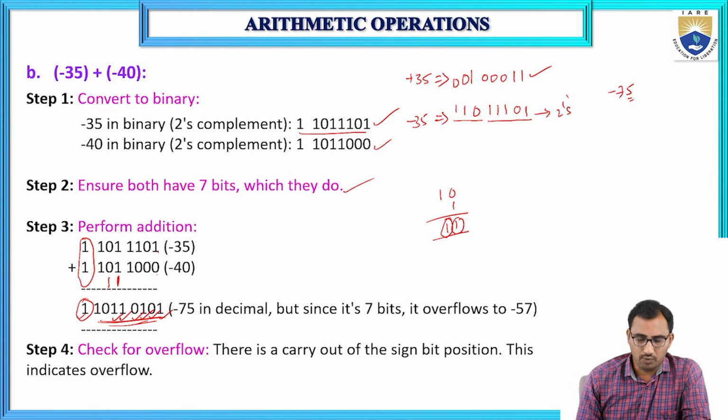Okay. So if you want this value, then for this data we have to perform the 2's complement. First we need to perform 1's complement. So 0, 0, 1, 0, 0. Okay. So for the actual value, leave the MSB sign bit and take the value.